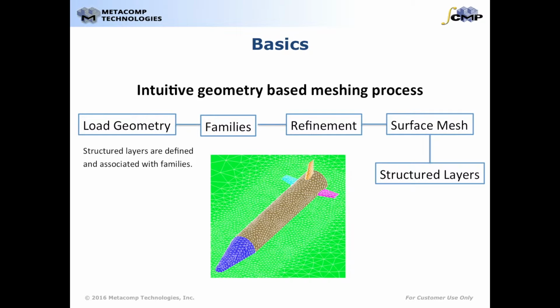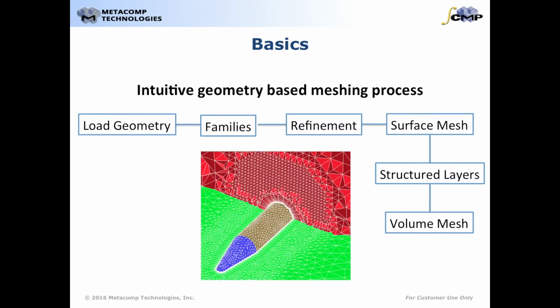If the user is satisfied with the surface mesh, then structured layers can be defined on a per-family basis. Finally, the volume mesh is generated. If the volume mesh is deemed acceptable after inspection, it can be exported and will become available for the solver.